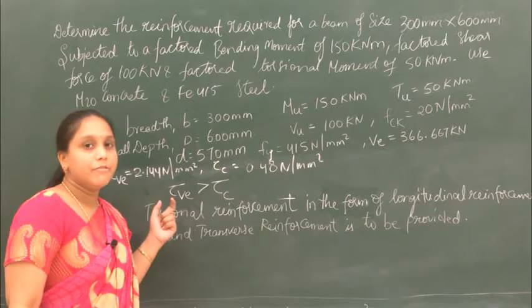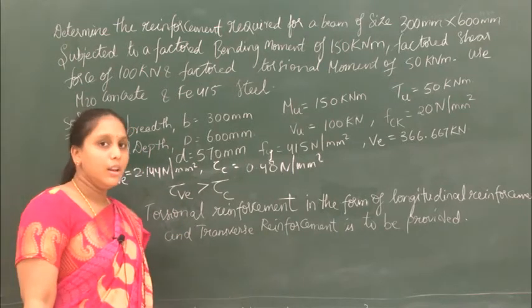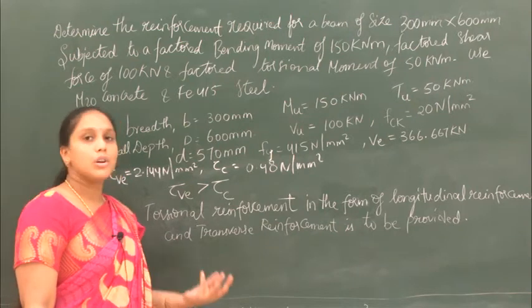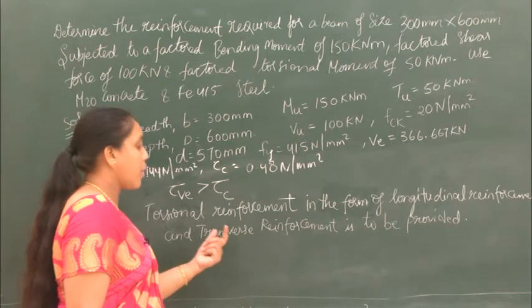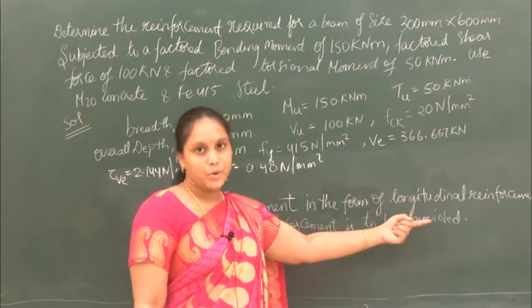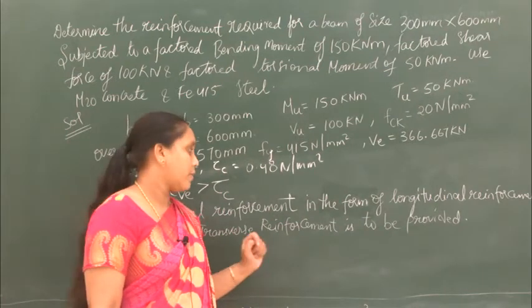You have to provide the torsional reinforcement, and how is it to be provided? That torsional reinforcement is to be provided in the form of longitudinal reinforcement and also the transverse reinforcement.